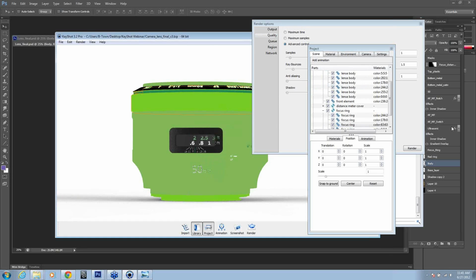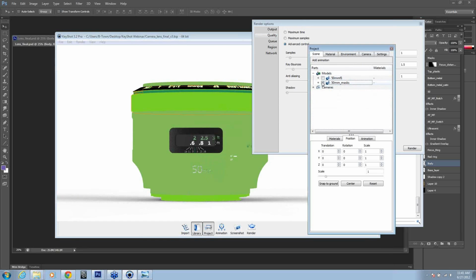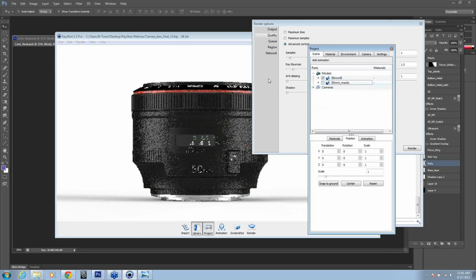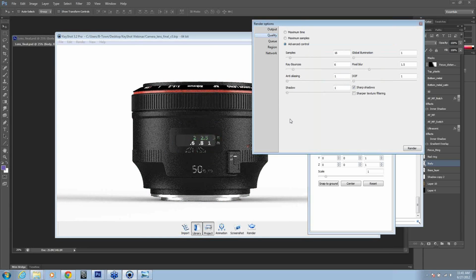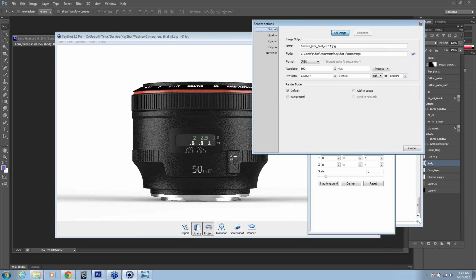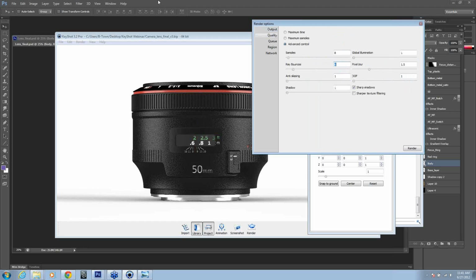Okay, when you get to the rendering portion, there are webinars out there that cover the render settings themselves. We are running out of time here, so I won't dive into those too much. But one of the nice things about rendering things at high resolution, say 4,000 pixels by 2,092 pixels, is you can go really low on these samples. Like you can set a value of 8.